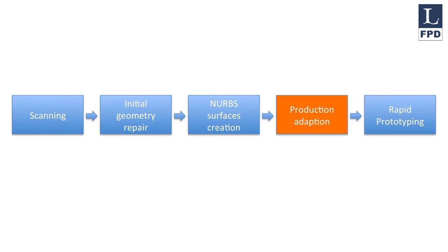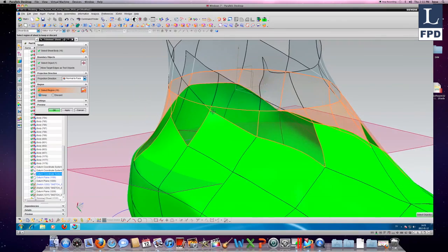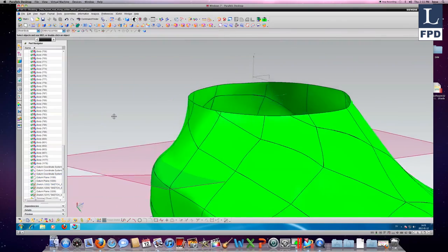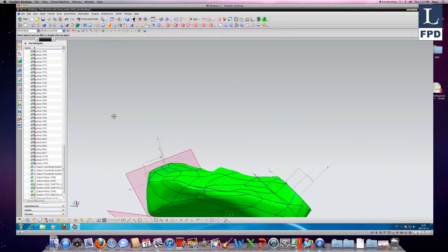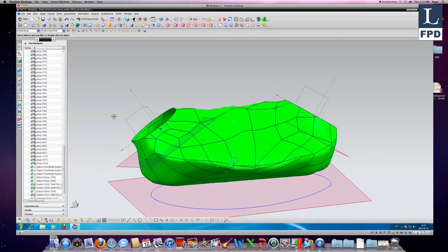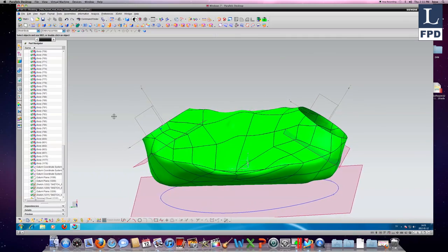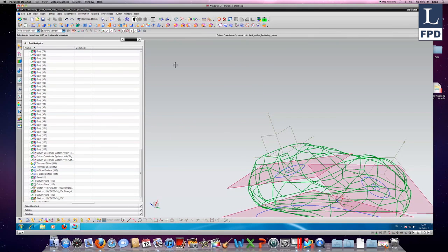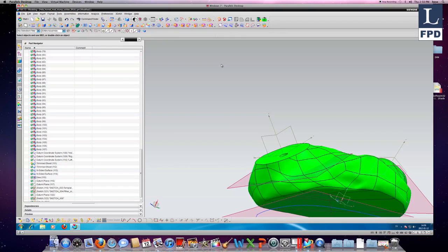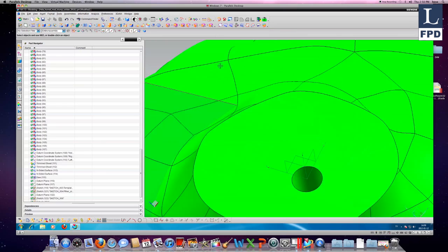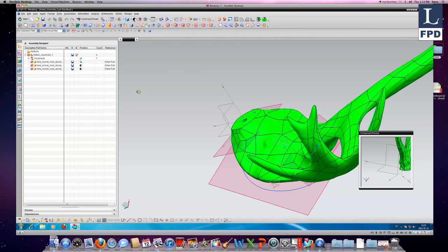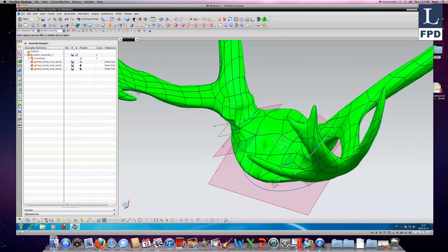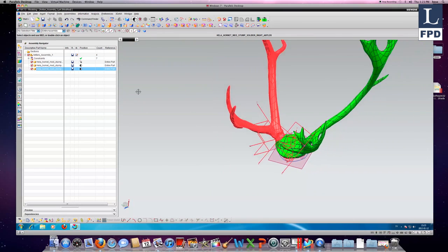In the fourth step, the step file is imported into a CAD software, where the geometry is split up to enable manufacturing. The reindeer antlers are too big to be manufactured in one piece using the injection molding machines of Nordpolymer AB. Therefore, assembly fastening devices are drawn in the CAD software and an assembly is created virtually to evaluate that the parts work together and finally produce the wanted antler shape. A STL file is exported, marking the end of the fourth step.